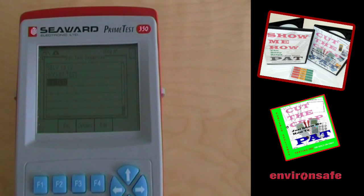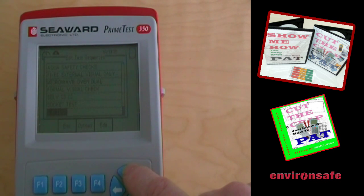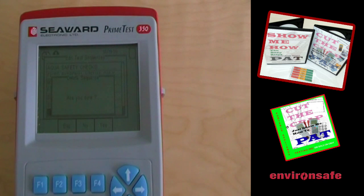that we've listed, and presumably you don't want that anymore. We'll escape that, go back to the menu, F4, scroll down to configuration, F4 to OK, edit test sequences, F4 to OK, and the SC test we no longer want. So let's see if they're in options. Yes, they are. We go to options, we delete the sequence, F4 to OK that. Are you sure? Yes, I'm sure. And that test is gone.